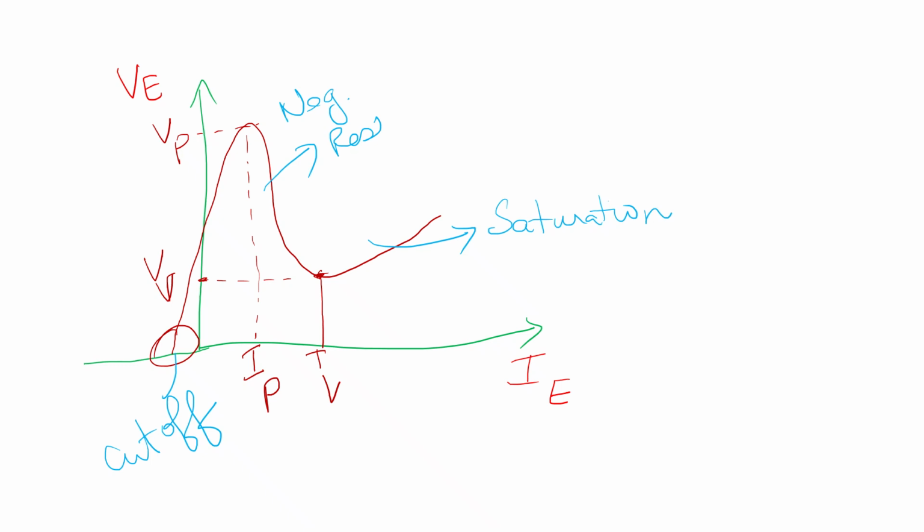So when a voltage is first applied, the unijunction transistor is off and the capacitor C1 is fully discharged, but begins to charge up exponentially through the R3 resistor. As the emitter of the UJT is connected to the capacitor, when the charging voltage VC across the capacitor becomes greater than the diode voltage drop, the PN junction behaves as a normal diode and becomes forward biased, triggering the UJT into conduction.